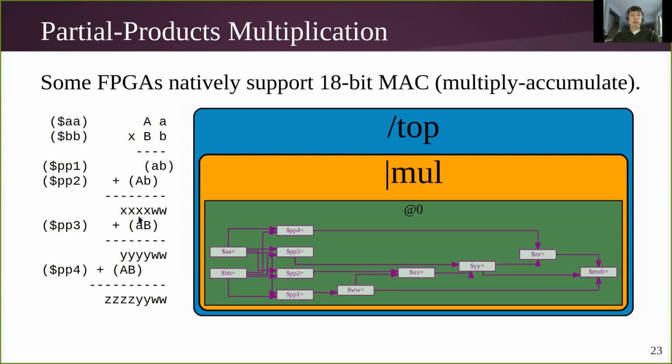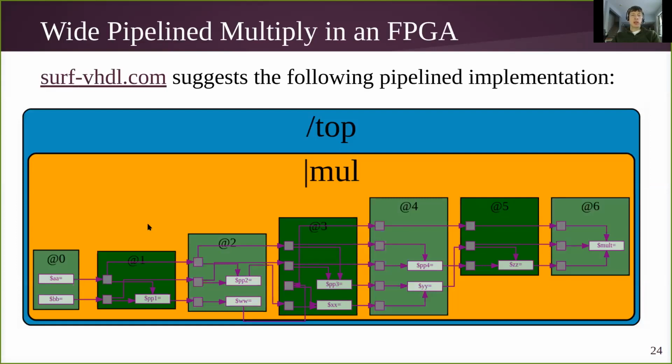And the blog post is proposing an implementation where in each stage of the computation, you're doing a multiply accumulate. Actually, I think the multiply accumulate is multiply in one stage, accumulate or add in the next stage. And each cycle of the pipeline, they're doing another multiply and accumulating that partial product into the result.